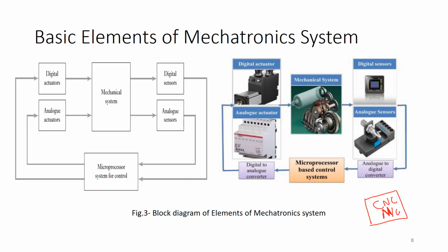Okay, analog form. So the 10 millimeter distance, again it is an analog value, a discrete value that will be required by the actuator. That means the motor will require the data in analog form. So understood that from digital form you need to convert it to analog form. So a digital to analog converter is placed over here.